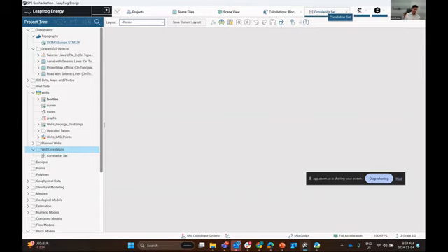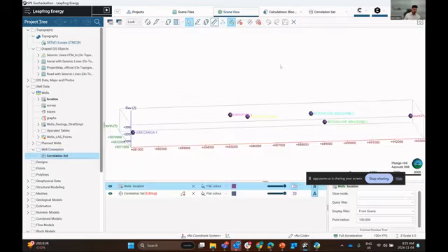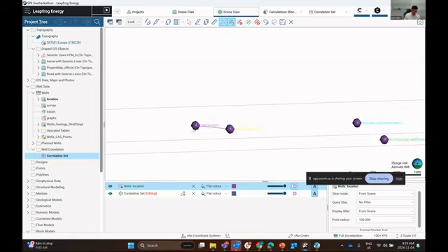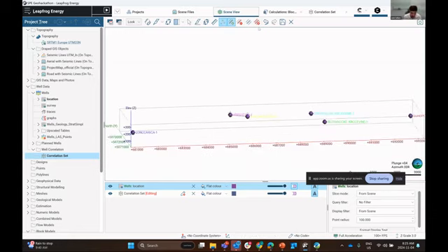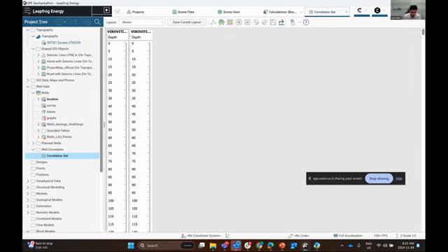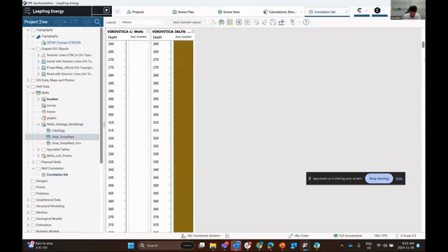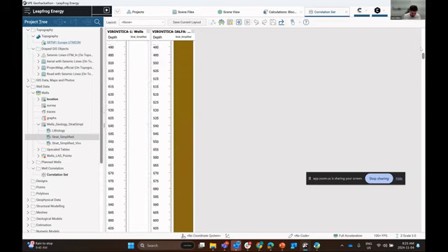To set up the well correlation set, you press this little blue triangle. So these wells that are kind of connected with these blue triangles, this is going to bring us back into the 3D view. You have to click that little blue triangle again, which allows you to select wells, and then you left click and left click. You see a little 1 and 2. If you press save, this has now added the 2 different wells to your correlation set, where we can add any kind of categorical information associated with the well that we're looking at.